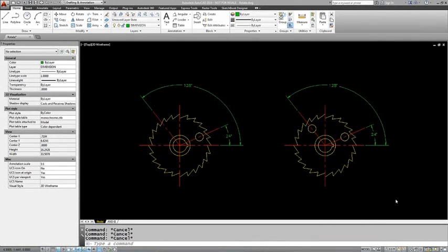Let's start off the hands-on portion of our presentation today by looking at rotate and rotate using reference angles. I have 3 examples for you. In the example on the screen now, on the right-hand side, we have an object that has 2 holes, and on the left-hand side, it's wrong. We need to rotate that one circle over at 128 degrees.